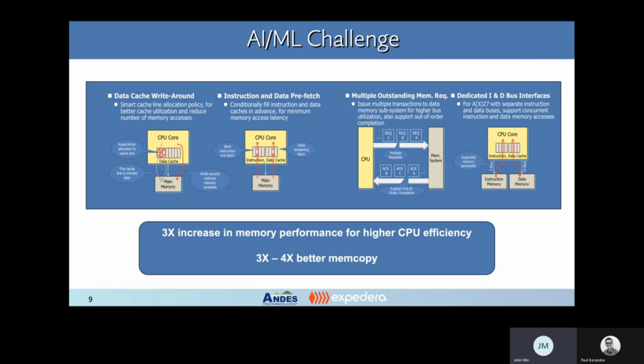Last thing we have is the old CPU paradigm. Do you want a von Neumann architecture, which shares address and data bus? It's great to make it very compact. It doesn't use a lot of pins. So it's really a nice architecture. However, instruction and data need to share that bus.